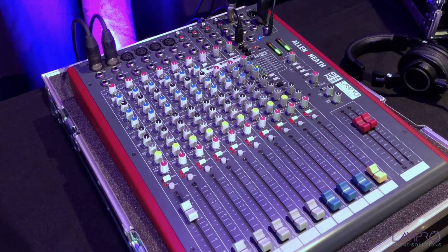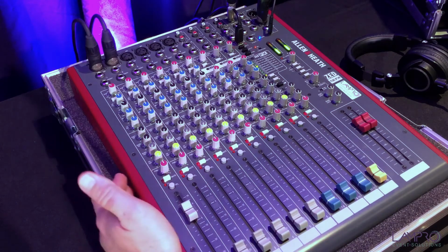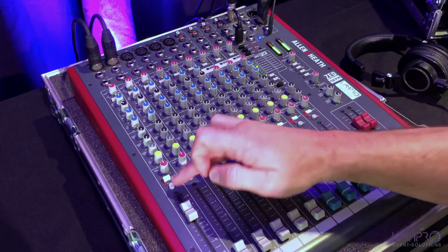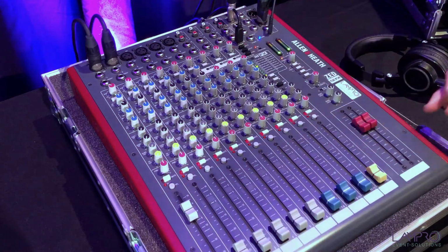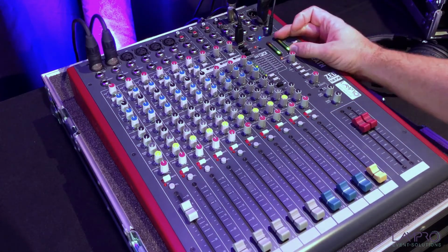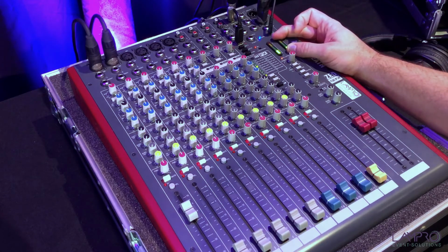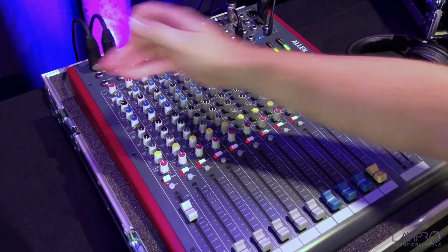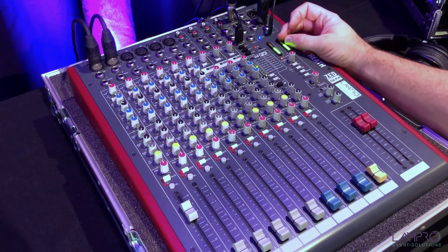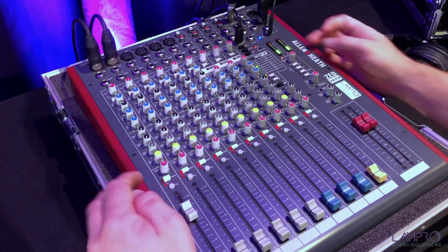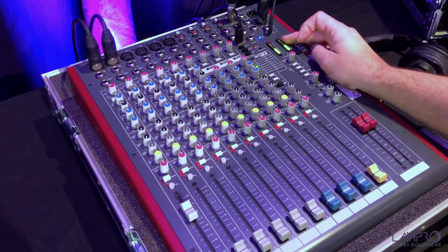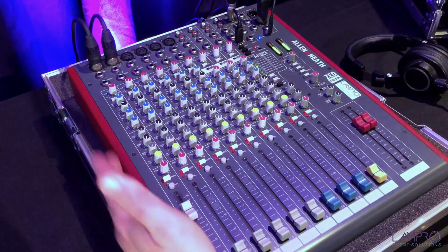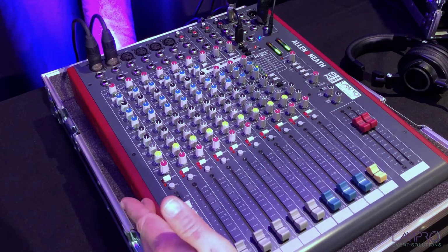So how do we set up a gain properly? Well, just to give you a demonstration quickly, if we hit the PFL button on channel 1 that's being used with my microphone, or the pre-fade listen button, you will actually see on the VU meter here the audio signal that's coming into the mixing console on that specific channel. Since the gain has already been set properly, I don't have to worry about any distortion taking place, and there's sufficient audio that's being sent out at the moment to the recording that you can also see, because the gain has been set correctly.